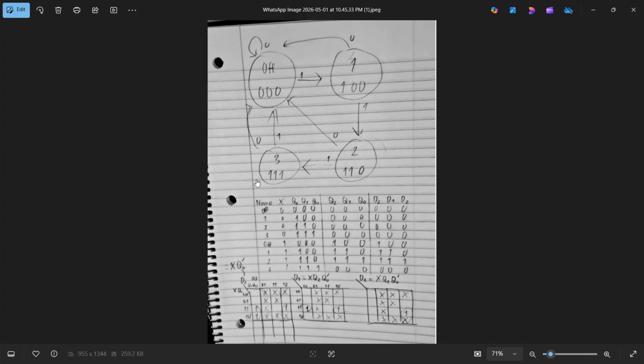Design choice, Moore versus Mealy. I chose a Moore machine. Output depends only on the state, simpler and more stable. D versus JK flip-flops. I would choose D flip-flops, easier to implement in Logisim, with direct mapping from the next state equations. 2-bit versus 3-bit. I would choose 3 bits, which allows direct LED connection, reducing decoding logic.